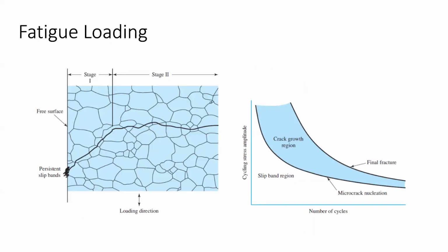Okay, so another really important thing that we encounter on the car is fatigue loading. In contrast to just peak loading, where you have a really high static load on a part, which is what most people tend to design around, fatigue loading is something that's relatively innocuous, but can really creep up on you. So about 4 years ago, we had designed a hub, and the hub is what supports the wheel load. It had this really sharp corner where the bearing interfaces with the abutment. As the car drives, there's a normal load on the wheel that pushes up on it, a relatively high normal load. Just at static, it's the weight of your vehicle roughly divided by 4, right?